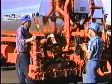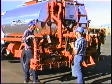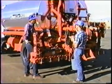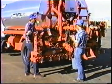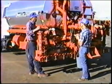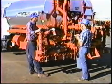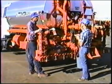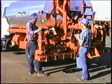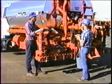Now if it takes 13 pounds of pressure in order to get the material from the bar to the ground in this particular wind condition, then you might have to run that hard. Also, just be aware that she's going to get dirty, because we're getting into the range that's creating overspray. If we're in a windy condition, that overspray is going to get all over our nice clean machine. If you stay down around 8 pounds all the time, it all goes on the ground. You'll get a little bit on the spray bar, and that's it. You won't get anywhere else.